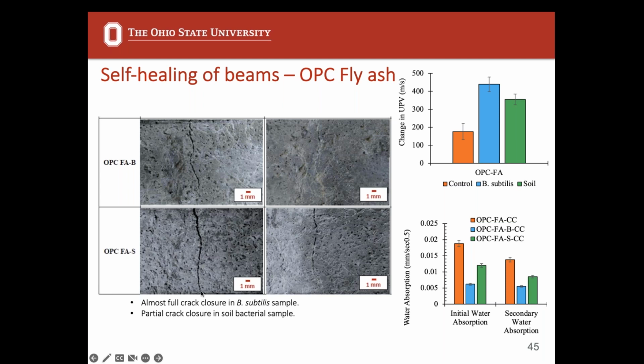So we induced a crack, and because they were fiber reinforced, it kind of held them together and closed it up a little bit. And then we sprayed it with curing solution. So no, these were not shrinkage induced cracks. We applied a force to the mortar bars in order to force them to crack.